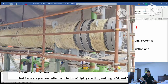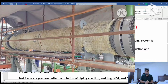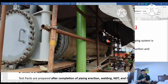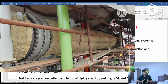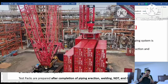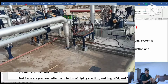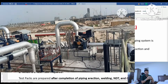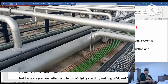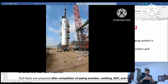Now I give you the second detail. Provide the complete documentation. A test pack provides you the complete documentation, meaning all the documents related to the piping system in one file. It helps in systemization, that is, dividing the plant. If you have one plant, you divide it into subsystem numbers, and each subsystem is then divided into test packs. It ensures quality compliance, meaning the test pack gives you confirmation that there are no quality deformations or quality issues. It also supports the final handover.